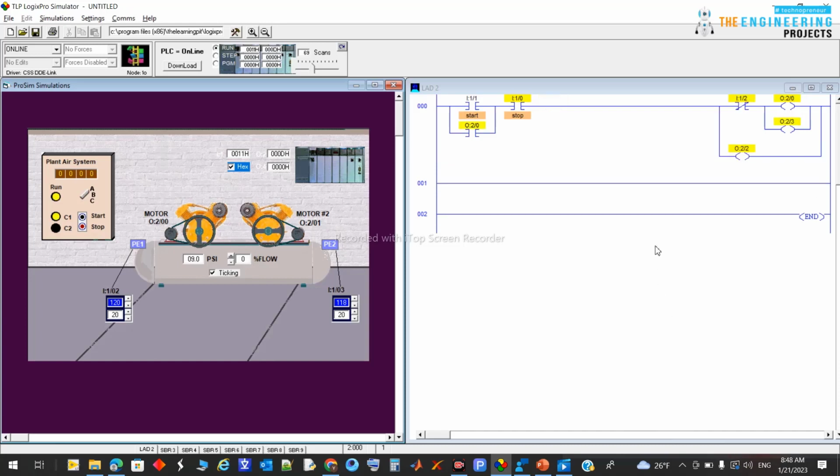Yeah, and finally I added some change to the logic. Like this is the start, okay, and by hitting the start, the run bit here is showing here. This is the run bit, okay. So at any time I can hit stop, okay. So the run is not running, and start. So the run now is running, and the compressor indicator C1 shows it is running, okay.